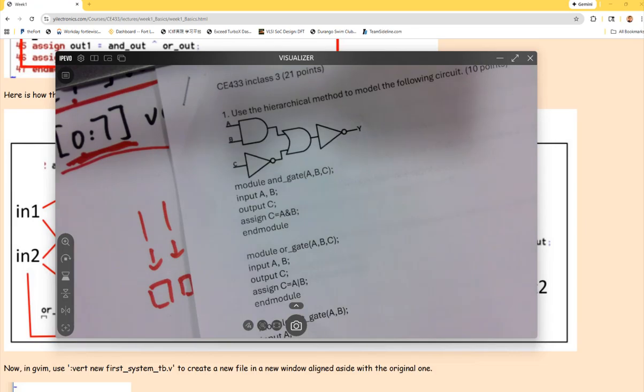Does that make sense? Imagine if the lower level ports were exported to the upper level. What's going to happen? There would be millions of ports with the same names. They would be physically shorted to each other, because all the ports of the AND gate are called A, B, C. So they shouldn't be exported to the higher level.